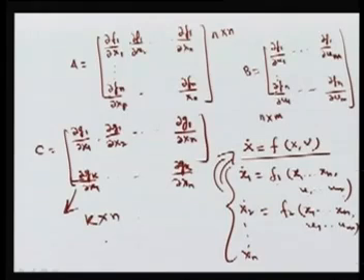Similarly we can write this D matrix, which is called the feed forward matrix, which defines the proportion of input which appears directly in the output, and the size of this is nothing but k cross m, because m is your input, k is your output, and n is your state. So it is just a definition that we can define.